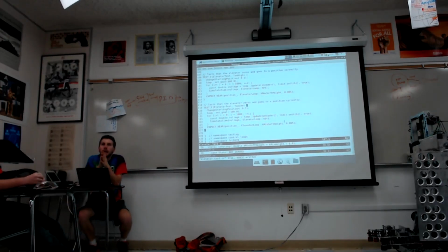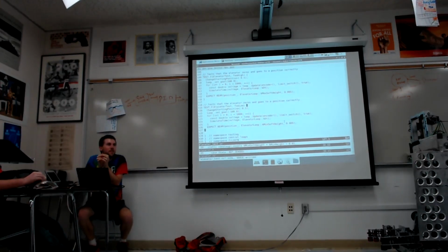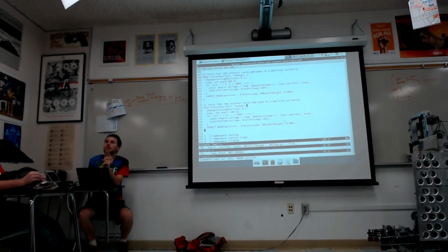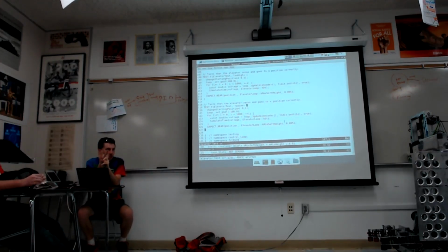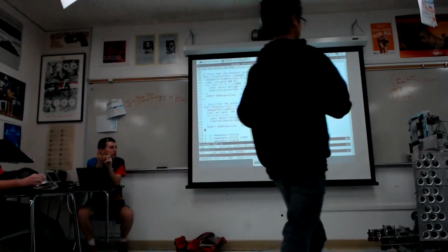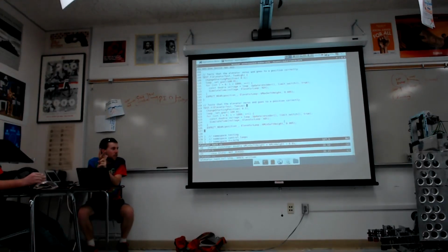Can anyone think of anything else we want to test before we go try this for real? So we've covered what happens if we don't start at a 0 point. We've tried going too high. We've tried going too low. We've done some control loop tuning. We verified that it respects the max and min voltages. Not coming up with anything else here.